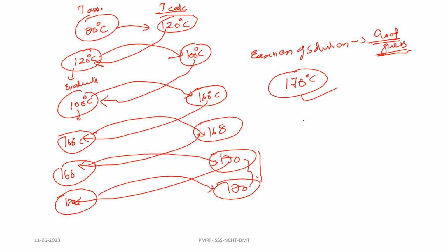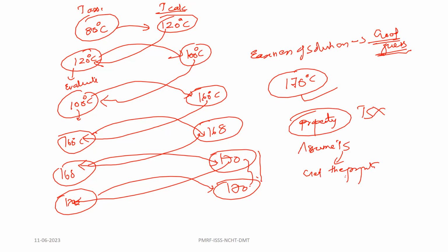So in such property determination, that's one challenge. When the surface temperature is not known, you have to assume a T_s, get the properties, calculate, and see how much the difference is in T_s. So I hope that is clear to everyone.